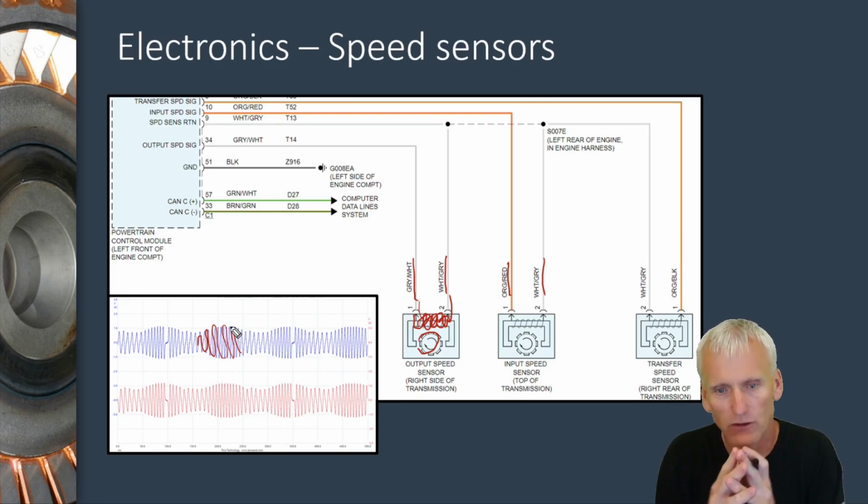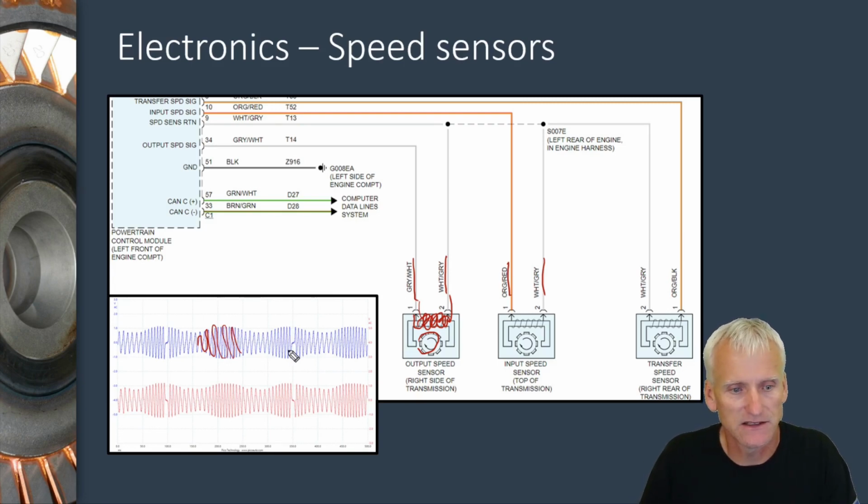If they're slowly expanding and contracting, we're not going to get a strong AC signal off of it, and therefore you're going to end up getting a poor signal or no signal. So that's the reason why you might find a magnetoresistive or a Hall effect type sensor in place of a variable reluctance, if they have to be able to monitor a shaft spinning fairly slow. But once these things get spinning at a certain speed, their output is usually strong.